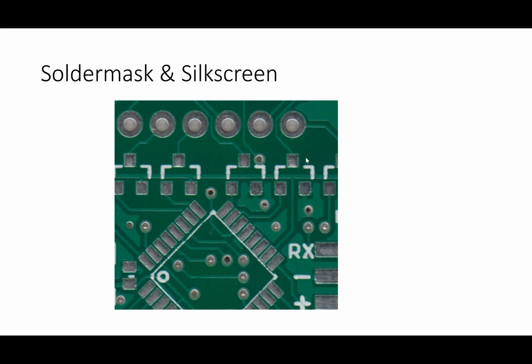All right, now I used a couple of terms there. I wanted to just show these things. Some of you, or hopefully all of you, have seen a PCB at some point. The solder mask here is that green layer of material. And if I look carefully at the board, these things here are called pads. Whenever I have exposed copper like this, it has that silvery look. That's a pad, and that's something to which I can solder.